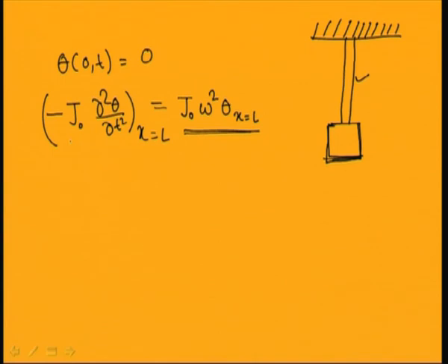So that is the torque. I can write this inertia force equal to G Ip del theta by del x at x equal to L. So this inertia load will be equal to the load at this end. So I can equate these two terms at this boundary to find the solution of the system, or to find the mode shapes of the system.